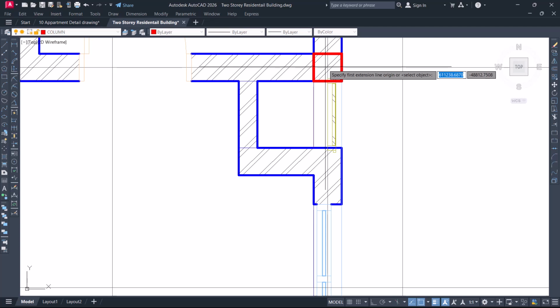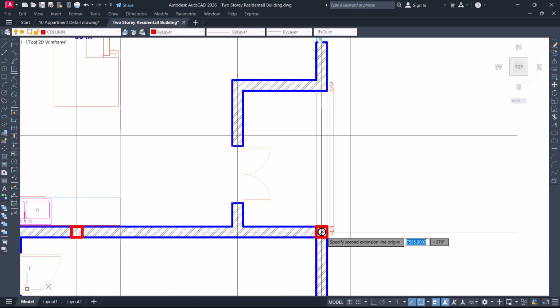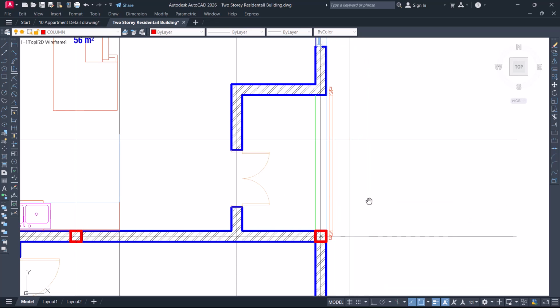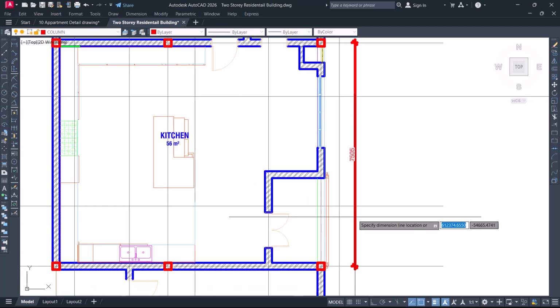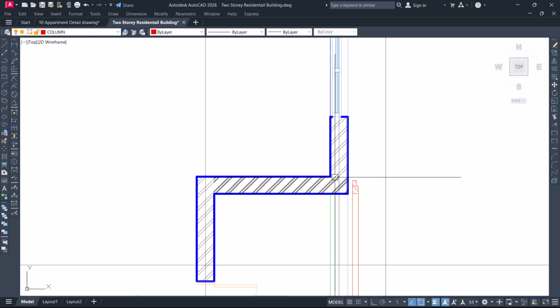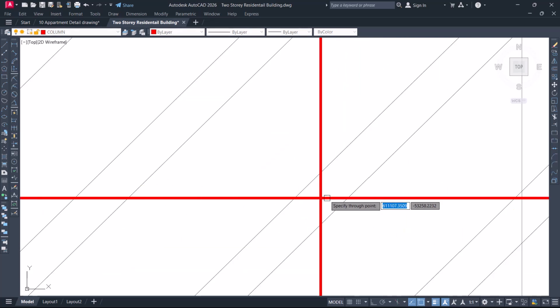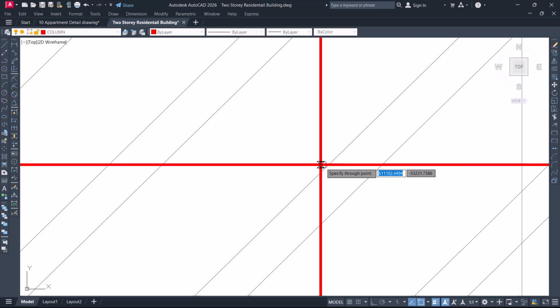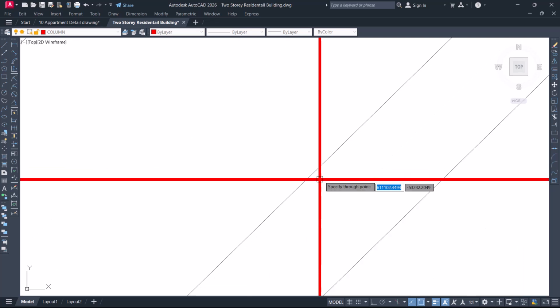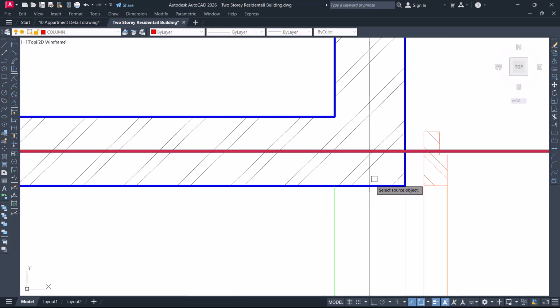And then let's see the distance between this column here. I feel it is too long. This column and this column here. That will be long. 7.5 meters, which is too big, right? Too long for the span. So with that now, we need to divide this span by 2. I'll divide it from this point here. So I'll come here and create a grid line, XL enter, H enter, and divide this. Look at this point, that's the middle. Then take off this and then MA enter, and I'll match this to this.